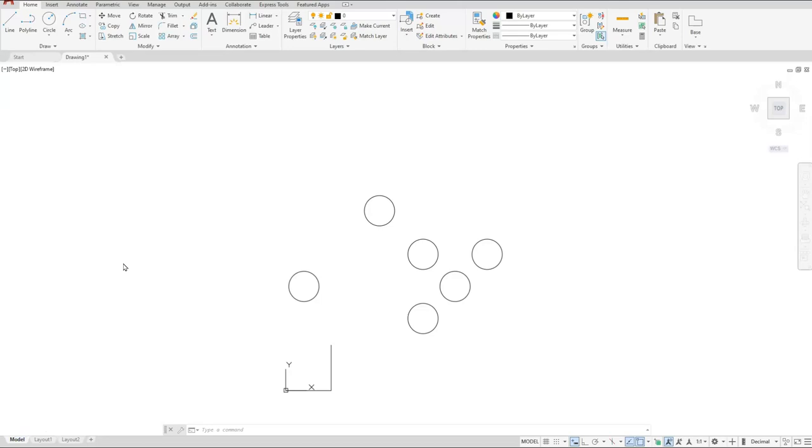Okay, so Ortho mode, we want to first make sure that we are set up in Ortho mode. One of our first ways of doing that is just by simply selecting the F8 button, and you're going to see right above your command line, it tells me that the Ortho mode is on. So that's the first way that I would look at it. If I want to physically look at a button, it's going to be the one that has the right angle, and that'll tell me that I'm in Ortho mode. And the last way is, like I said, if I'm in like the line command or something of that nature, if I'm dragging my cursor around, and you can see these lines will only go up and down and left and right, that's another way to verify that you're in Ortho mode.